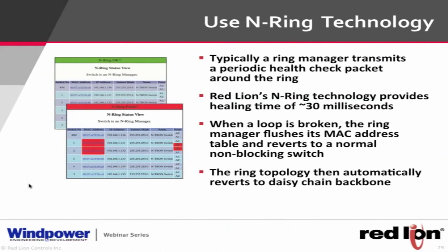So using the in-ring technology, the ring manager sends a health packet around the ring to make sure that it's intact. Once it fails, it does a repeat attempt a couple of times, and then at 30 milliseconds, it will heal. So if it's broken.